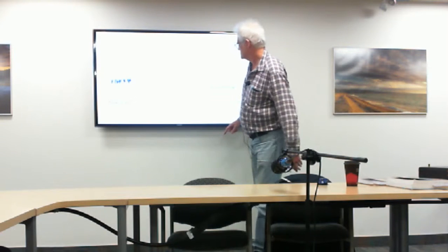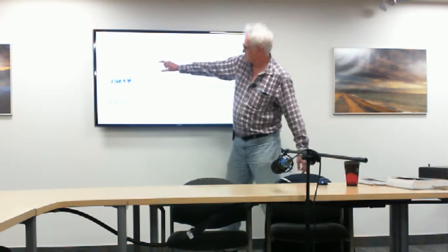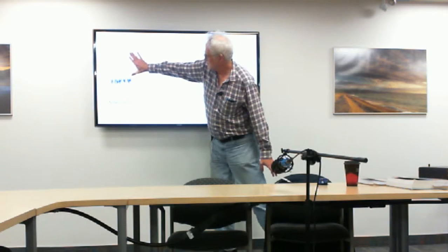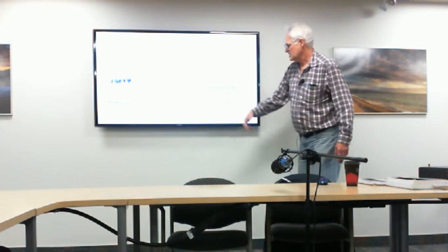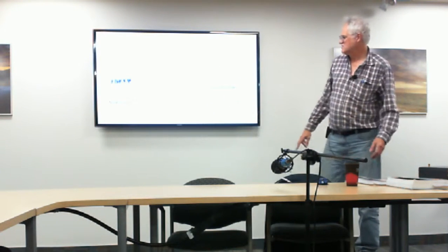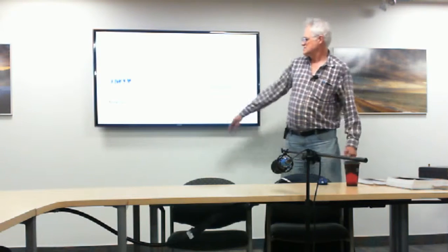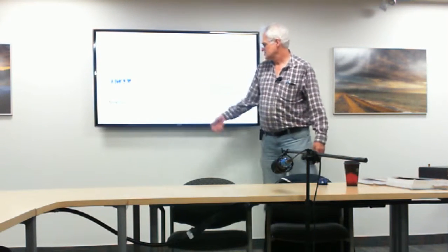When we talk about signal to noise, as I mentioned before, we're talking about comparing the level of our actual desired signal to the value of the noise signal. And we do it as a ratio. Everybody loves mathematics, but we do it in decibel form, or 10 times the log of the signal power over the noise power. Or typically, let's mention the signal plus noise to noise.